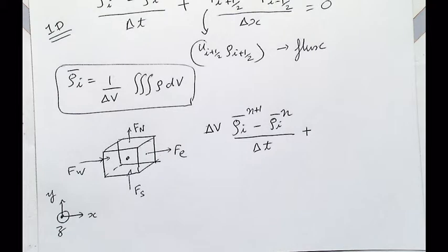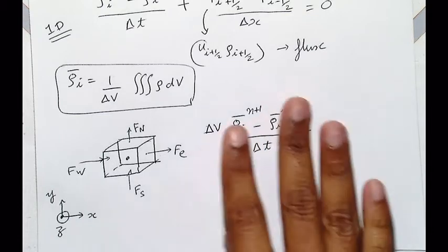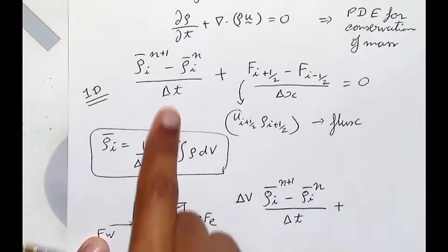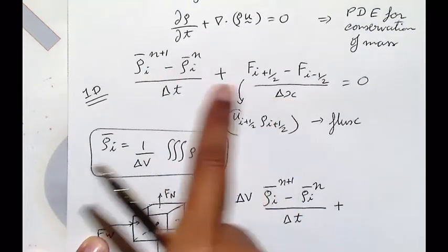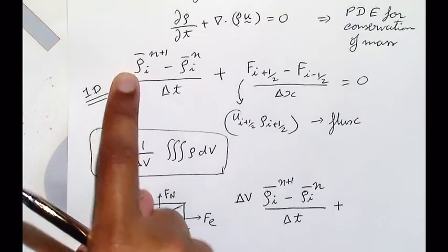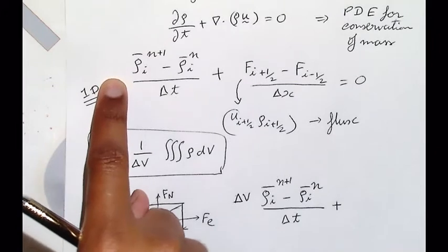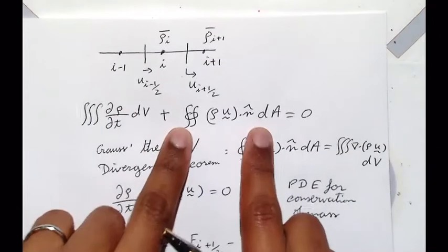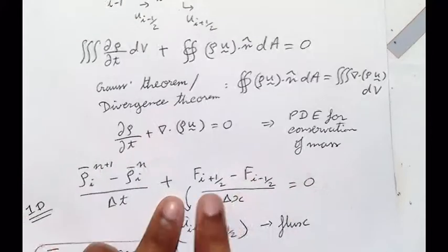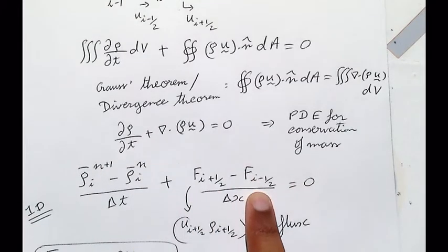Right. East minus west over delta x. Where did the delta x come from? From the west to the east. No, so see, try to relate this term to this term. So delta x actually originated over there. Okay, so in 1D, delta v is actually delta x. Okay? And the surface integral has no delta x, it's just flux east minus flux west.